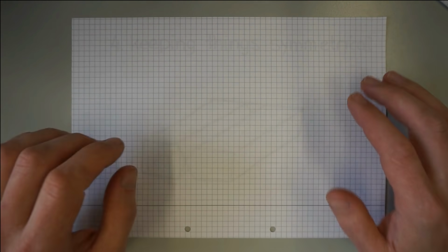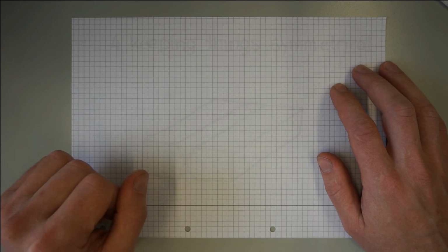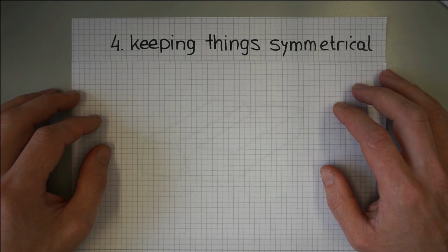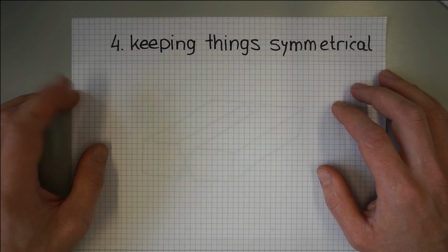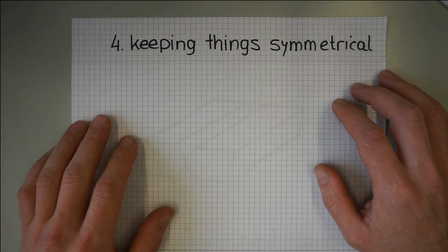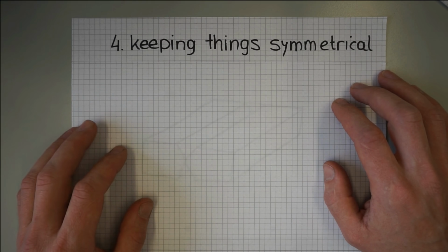You almost made it through this episode's talking part. There is but one sidekick strategy left. It's the method of keeping things symmetrical. This means not just the workpiece geometry, but also means heated spot location and movement during welding.